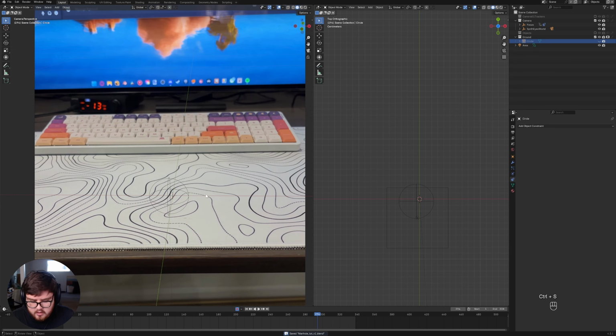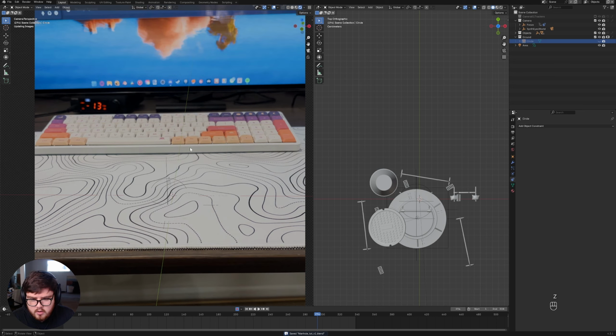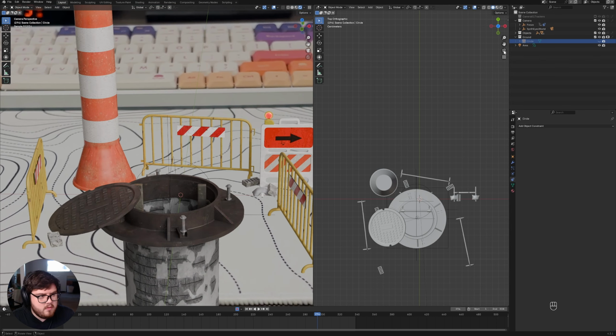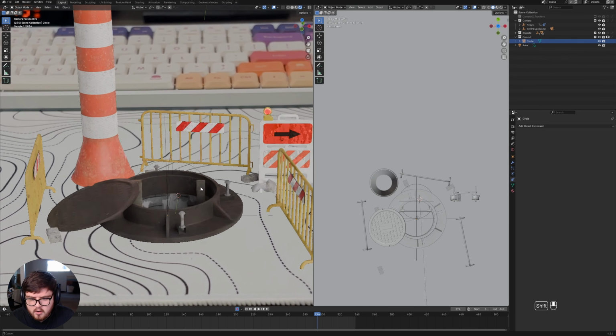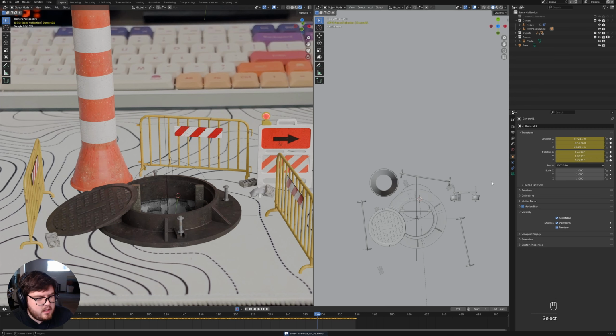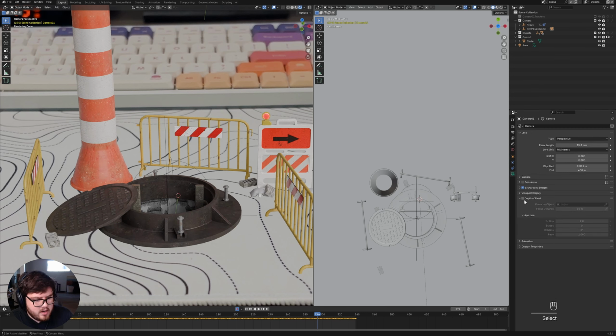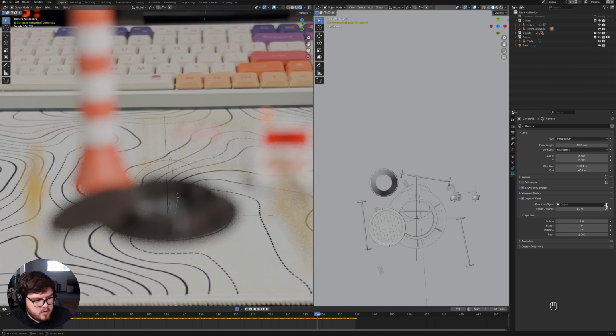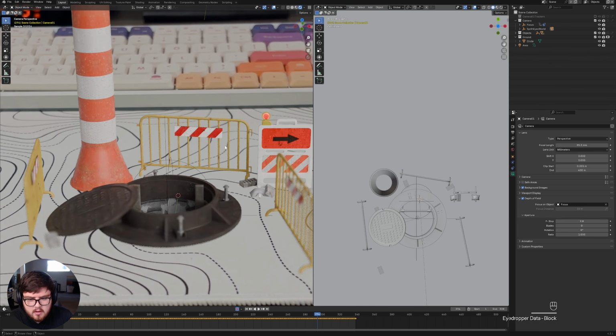Let's go ahead and apply this focus as well. So I'll get the objects back and go into rendered view. I do want to see what it's doing first of all, and then unhide our ground plane, which I accidentally did. But yeah, now we have the focus empty. We need to make that actually work as a depth of field. So for focus on object, we're going to put our focus empty right there.